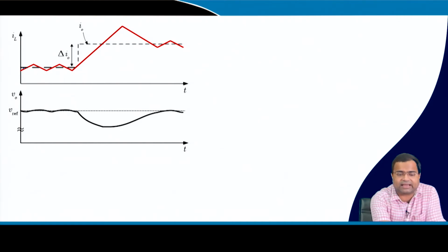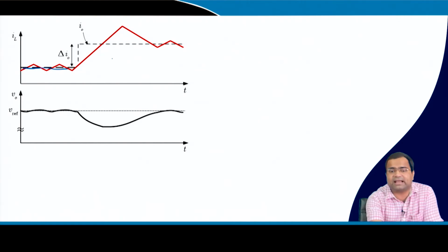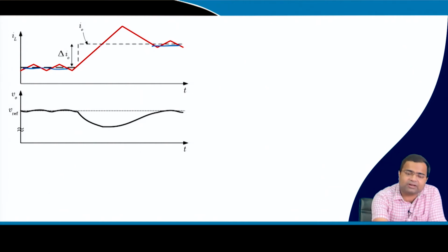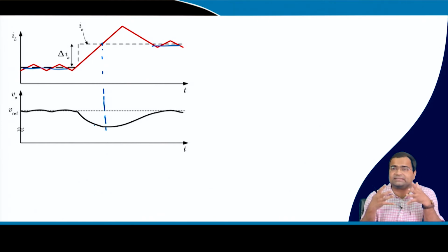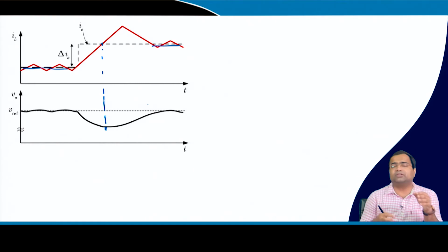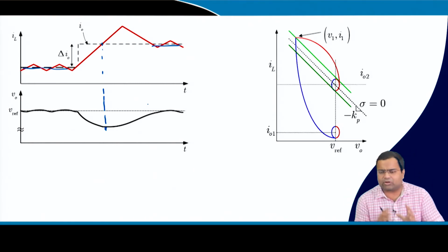Okay. So, now coming back to our time domain waveform in time optimal control, where the inductor current average was here, and you need to achieve the next average current here, and there is a ripple current, right. And as long as the inductor current is smaller than the load current, your capacitor current is negative, and as a result the capacitor voltage will dip. But once it crosses, then your capacitor voltage will slowly increase. Okay. And this is the corresponding phase plane diagram you can think of.